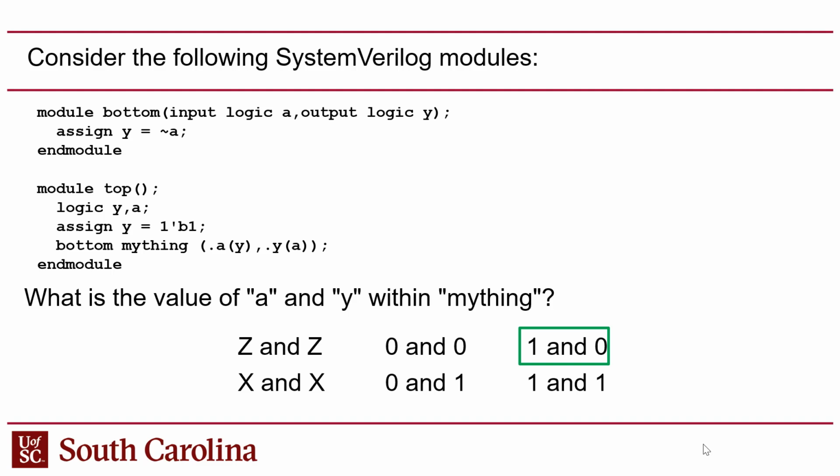VHDL don't care is a dash, a hyphen. And undefined is a U, meaning not initialized. And contention is an X, right? So VHDL has 6 states, Verilog only has 4, but if you use Verilator, which is a really popular thing right now where you can compile Verilog and actually run it on a computer, on a Linux machine, then you only get 2 states. So if you have any weird things in your design that would normally be caught by finding X's, you're in trouble because you're not going to find them.